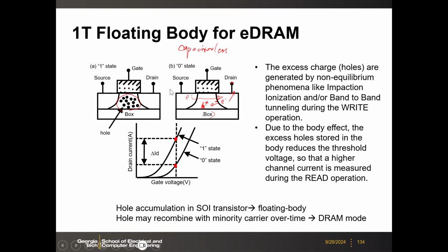So this is at least one proposal. Still, there are many challenges to design the EDRAM with these floating body effects, like cell-to-cell coupling, retention, and so on. So this is not widely used, but at least there's a concept like this.